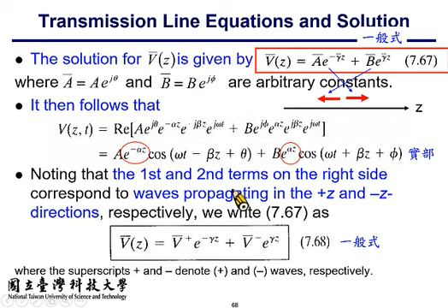Alright, so equation 7.60 is the general expression in which form? Phasor form, for the transmission line signal on the line, right? So you have V plus and V minus, which represent the component that goes to the right and the component that goes to the left. Okay?